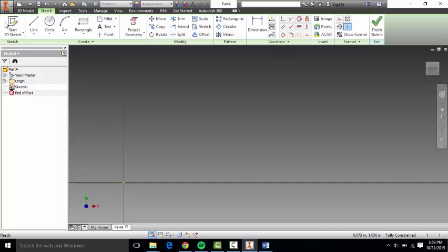Okay, let's go see the rectangle tool. The rectangle tool will prompt you for the selection of the first point. So I'm going to select the coordinates of my x and y point. I'm going to make them 1 and 1, so I press tab, and then tab again to get to the y coordinate. Okay. And I'm going to try to make this rectangle a square. So let's have it be 2 inches, and tabbing to get the width by 2 inches.